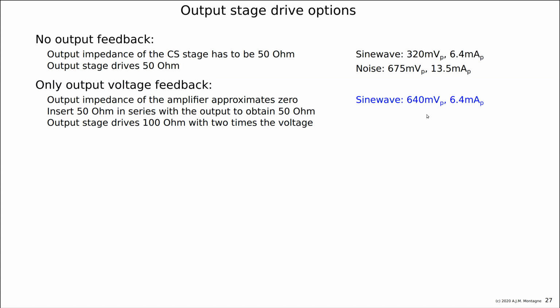And remember, we have a 1.8 volt power supply. So if you do this and you have to deal with a Gaussian distribution of your input signal, so it is like noise, then it was already 1.3 volt peak, which is 2.6 volt peak, and we have a showstopper because this doesn't fit in 1.8 volt, unless, of course, we now go to another scenario, which is applying a transformer to bring down the load impedance seen by the amplifier.